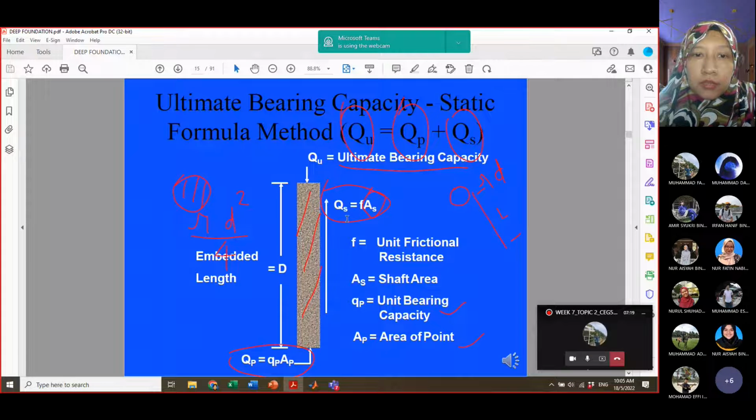By definition or by concept, assuming that you have a slender structure called a pile, the basic requirement is that the pile can go more than 3 meters depth. That is the first thing you need to be familiar with. Then in terms of the design requirement, we look at shear failure, then the limiting settlement, and there are three items.